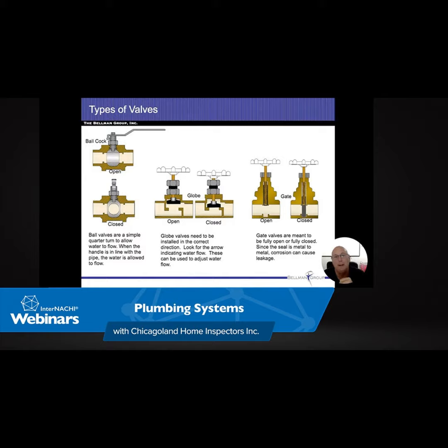And they're going to pour that lead on top of the oakum in that gap. And that's what's going to make our watertight seal. Sometimes that oakum will start to boil, and then that'll come up and over the top, and it'll look like there's brown stains that are coming off of that gap, all right? And if you don't know what you're looking for or don't recognize it right away, I can honestly see how somebody would think that that's a leak at that joint, when in all reality, it's oakum, all right?